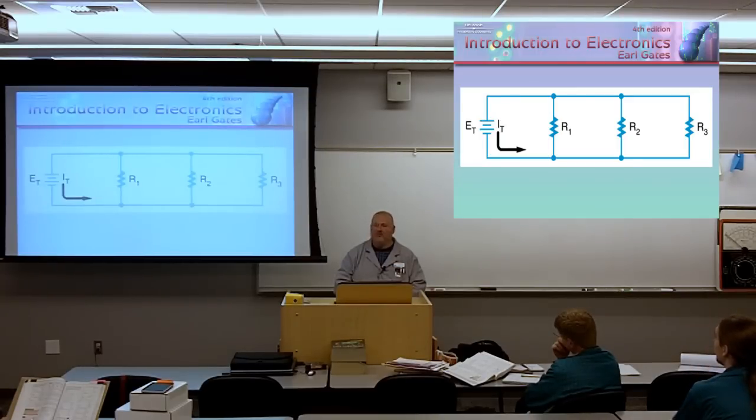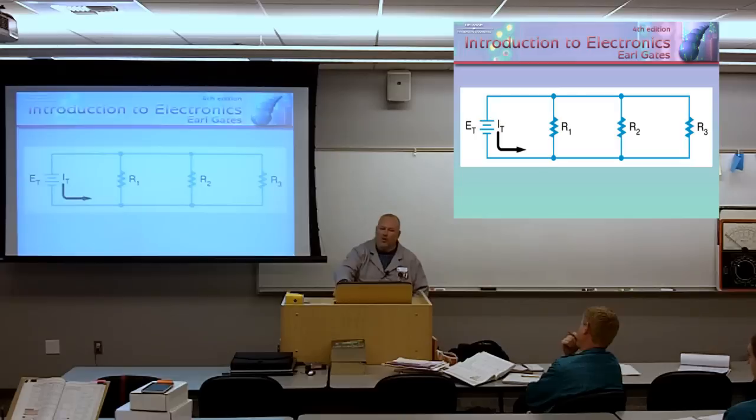But I could tell. If I brought you back there, you probably wouldn't even notice it. But I could tell which light is the furthest from the power supply, just looking at it. And it kind of bothers me. It doesn't bother me enough to rip up the conduit and pull new cable, okay? But I know by looking at it. And what does that tell me? That tells me that the load furthest down the line is not getting the same voltage as the load closest to the source. And gradually, as you get further away from it, you just notice a little difference in illumination.